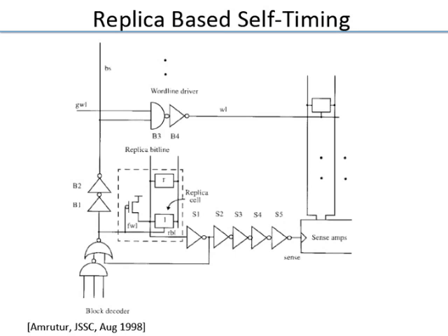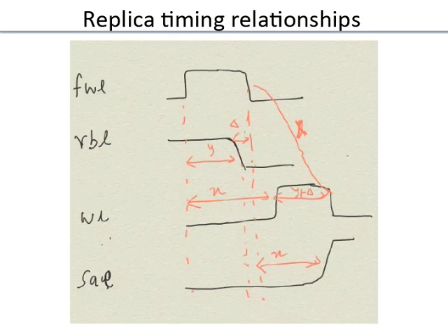There can be multiple delay stages there. This is just buffering. Because you generate the signal and you have to buffer and drive so many sense amps, you'll naturally have some buffering required. This is intended for optimizing the delay, since you have to have buffering, but now you need to, of course, control the sizing of these and optimize the delay. We'll look at that next, right?